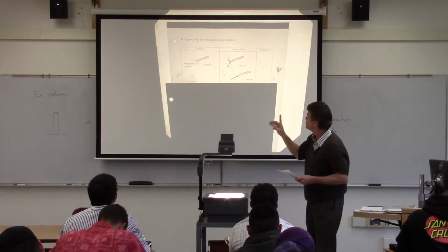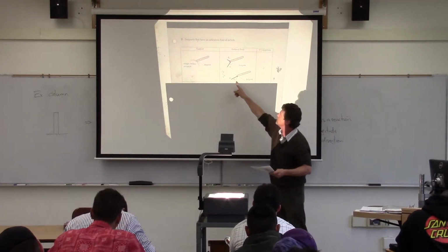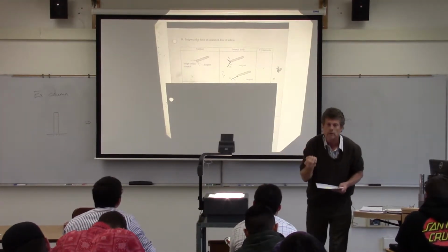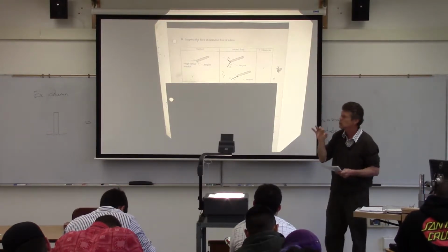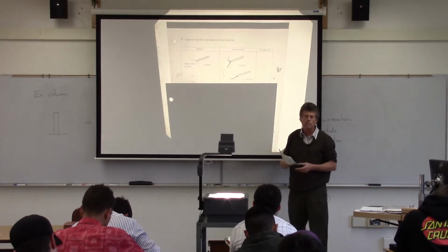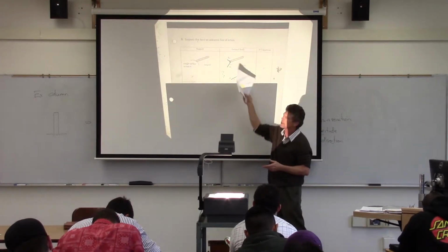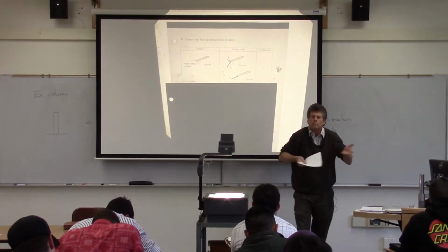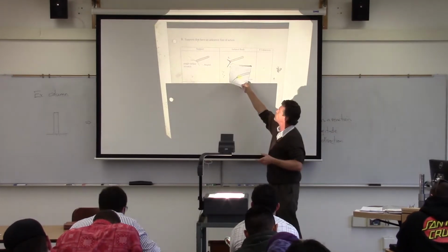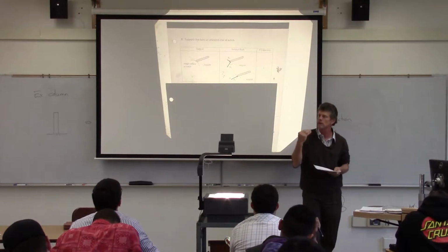Okay, so we're substituting in one force. The force has an unknown, it's a vector, though, so it has an unknown magnitude and an unknown direction. So we can show it this way, but most of the time what we're going to want to do is break it into x and y components, because we're going to want to plug those into those scalar equations there. So this isn't two forces, it's two unknowns of the same force.